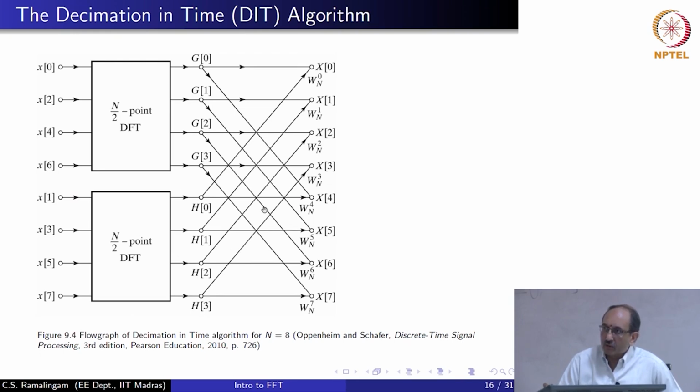Now immediately it should strike you, by going from an 8-point DFT to two 4-point DFTs, you saved computation. But now you need to compute these individual 4-point DFTs. Again follow the same idea, take the two 4-point sequences, again divide them into odd and even parts, and instead of doing the 4-point DFT, do the 2-point DFT. Now you will have 4 such sequences. Therefore, if you have a power of 2, you can do this log n to the base 2 times, alright.